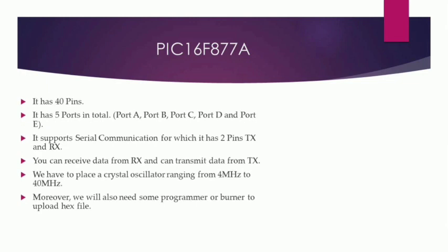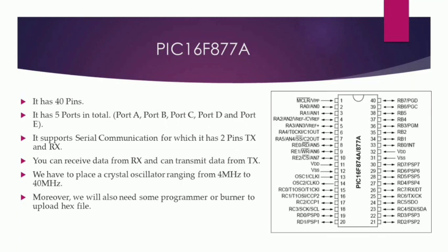Next we move on to PIC 16F877A. It has 40 pins. It has 5 ports in total: port A, port B, port C, port D and port E. It supports serial communication, for which it has 2 pins, TX and RX. You can receive data from RX, and you can transmit data from TX. We have to place a crystal ranging from 4 MHz to 40 MHz. Moreover, we also need a programmer or burner to upload the hex file.